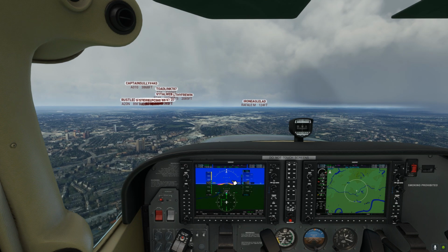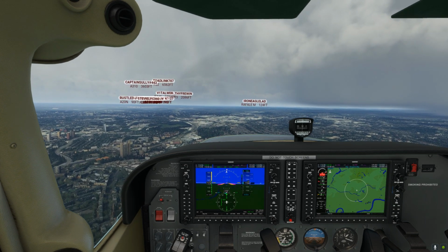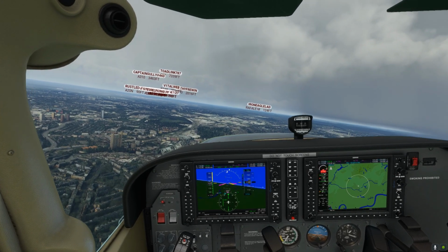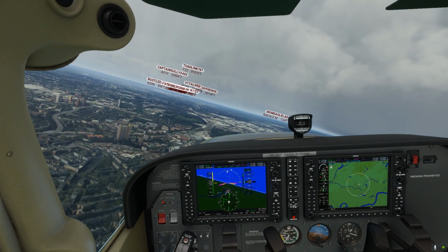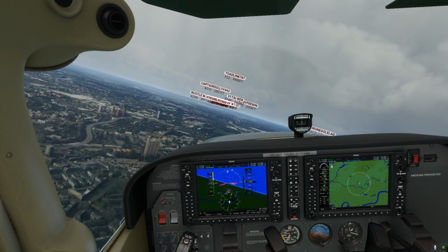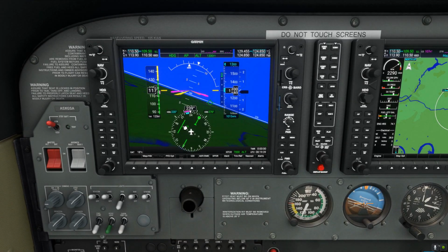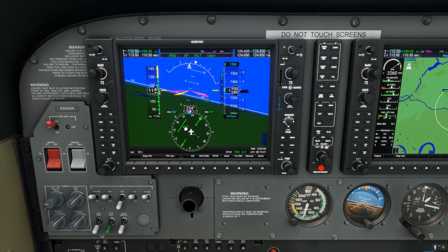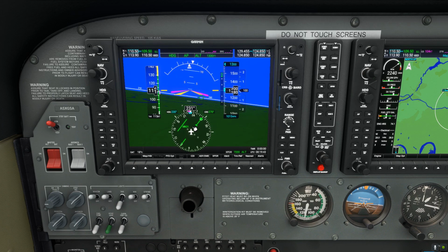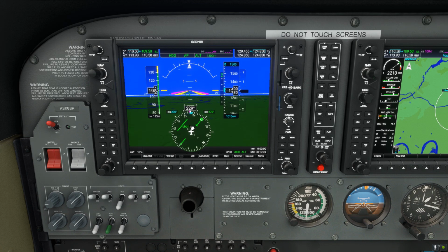And I'm just going to check. I'm about 10 nautical miles out, so I'm still in heading mode. I'm just going to move my heading to the left. Let me just slow down my aircraft. Overspeed there. Just move my heading bug to the left there. And essentially what I'm waiting for here is for that course deviation indicator, the line, to come in so I can join it up with these other lines, which means we'll be heading directly for runway 27.